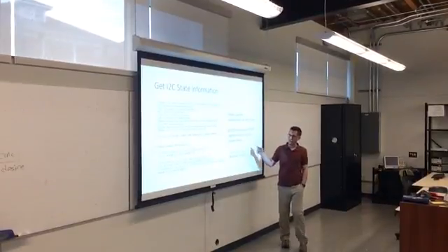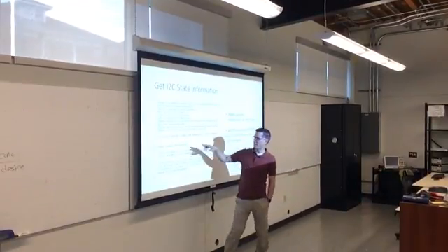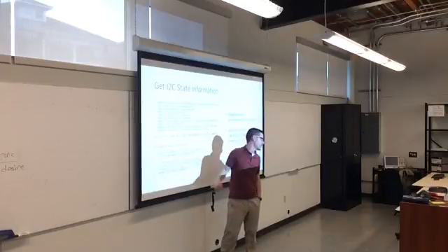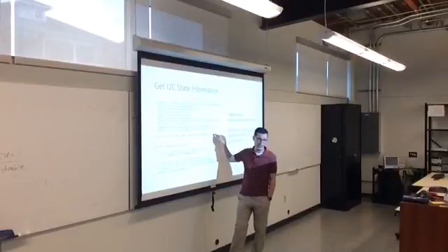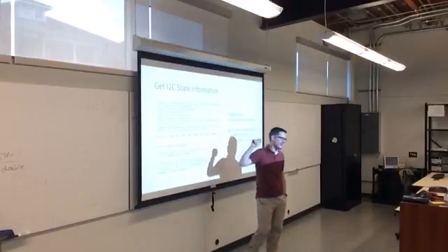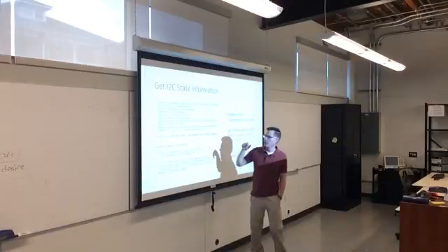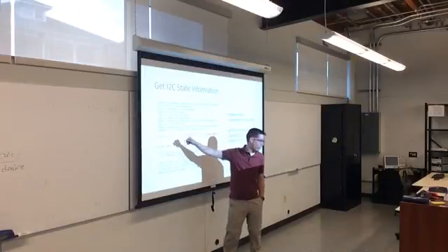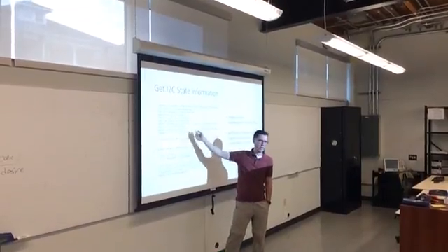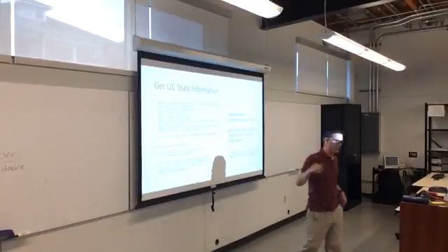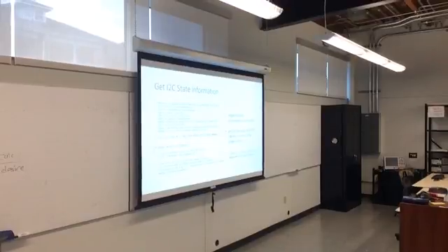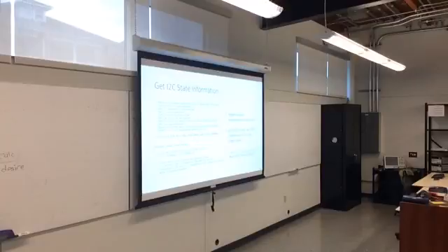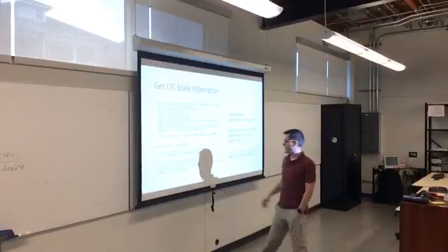And if you look at the way that state register is laid out, a 0 response means idle. A 1 response means wait. A 2 response means start. Because the enumeration is in the exact same order as those bits, and those bits are in contiguous order, you can do this. So it's a neat little hack to sort of make the code more readable. So what I do is I take those bits, those 3 bits, I shift them down, I AND it with 7 to kill everything else. I cast it as the enumeration, and I return it. So you get that function.